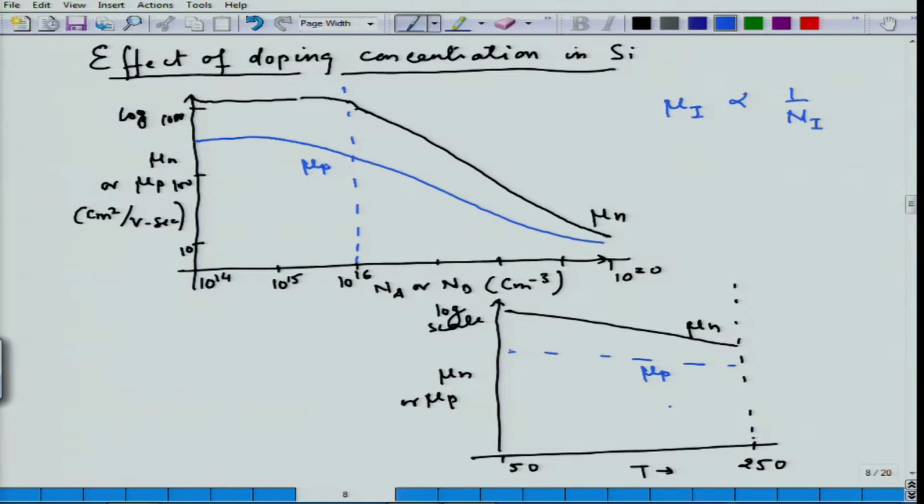Over here we are basically seeing the effect of the lattice vibrations for a given dopant concentration. So, unlike what we had shown in the temperature effect, it first increases and goes down. What we are seeing is only the effect of the lattice vibration, where the mobilities continue to decrease with temperature. So, these are the typical values of mobilities that you will see in semiconductors. So, if your dopant concentration is changing in the device, or if the temperature is changing, then one must use the expressions where the mobility is to be corrected for the given dopant concentration and temperature.